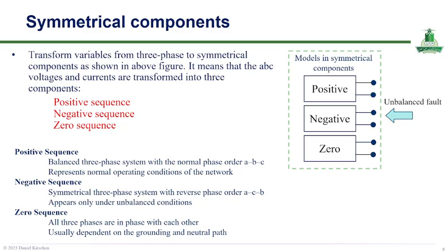The idea is to transform the original three-phase voltages and currents into three separate components: positive sequence, negative sequence, and zero sequence. The positive sequence represents a balanced system with a normal phase order ABC, similar to the balanced case, and reflects a standard operating condition of the network.